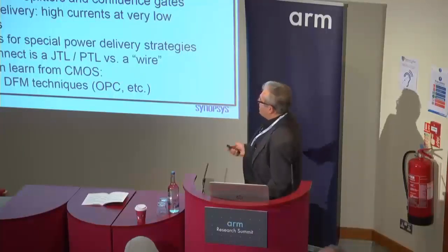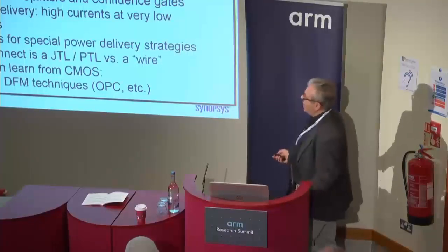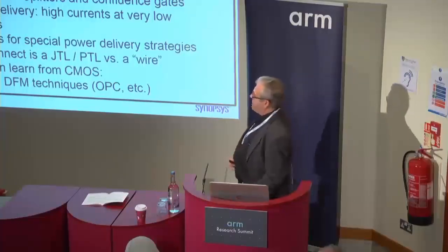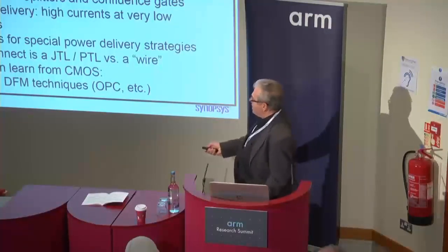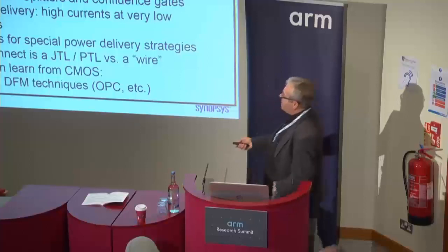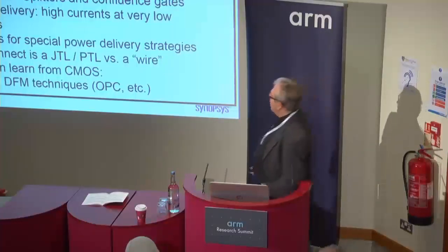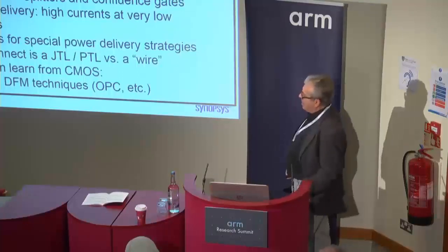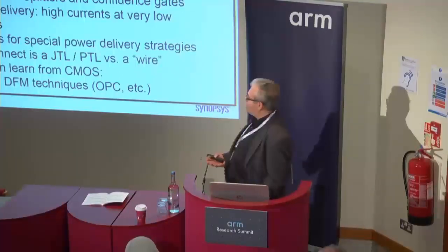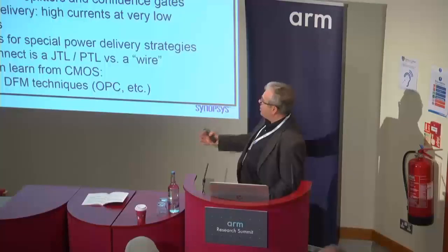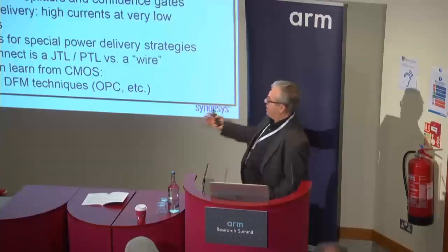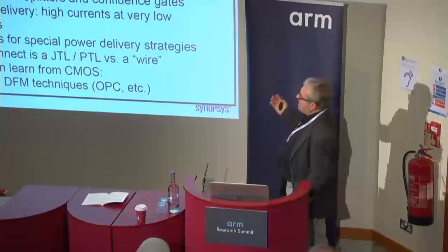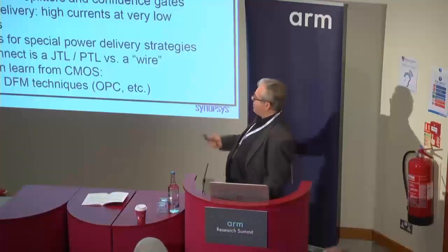The other thing, an area that's still lacking big time that we hope to borrow from CMOS, and we have a lot of knowledge in it, is DTCO and DFM. DTCO, which I will be stressing a lot in my talk, stands for Design Technology Co-Optimization. It's a technique or a methodology to shorten the duration needed to develop a technology from, let's say, a year to less than 3 months and so on.